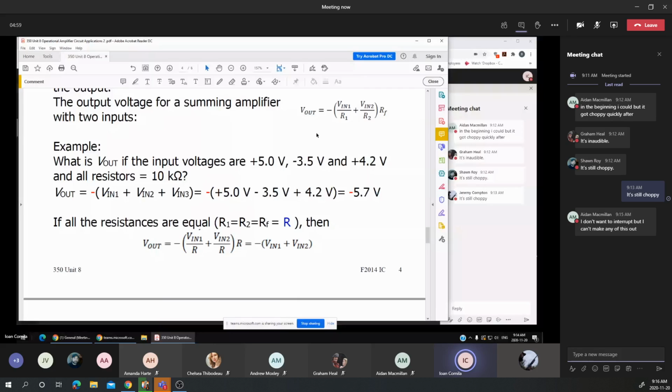We have a summing amplifier by simply using the equation, choosing the resistances R1 equals R2 equals Rn, and if we make RF greater than R, we'll still have a summing amplifier with a gain of 2, 3, or 4, and so on.